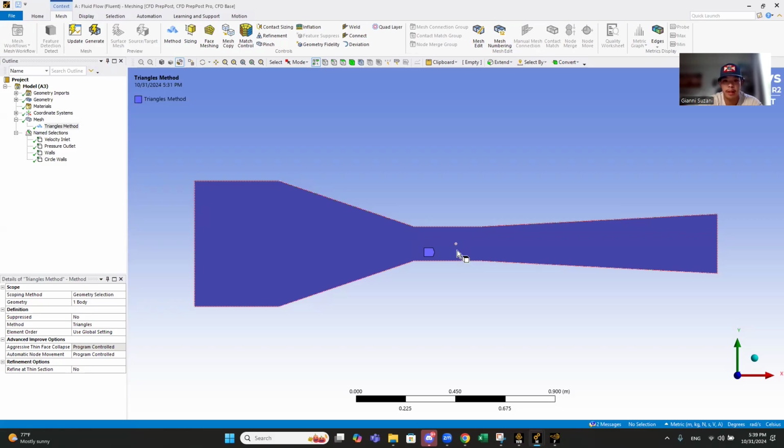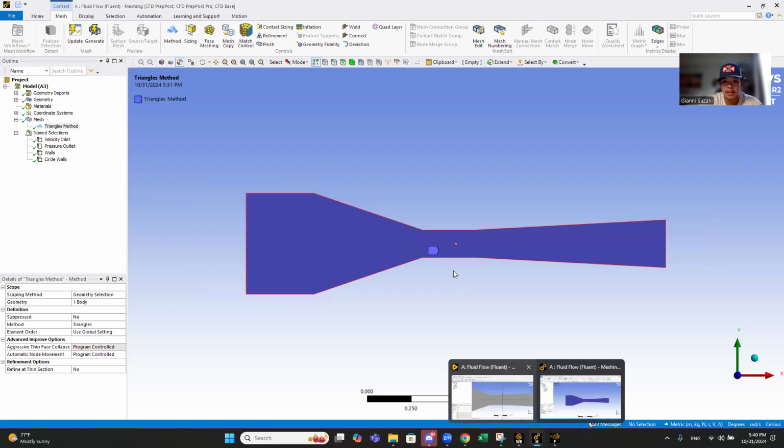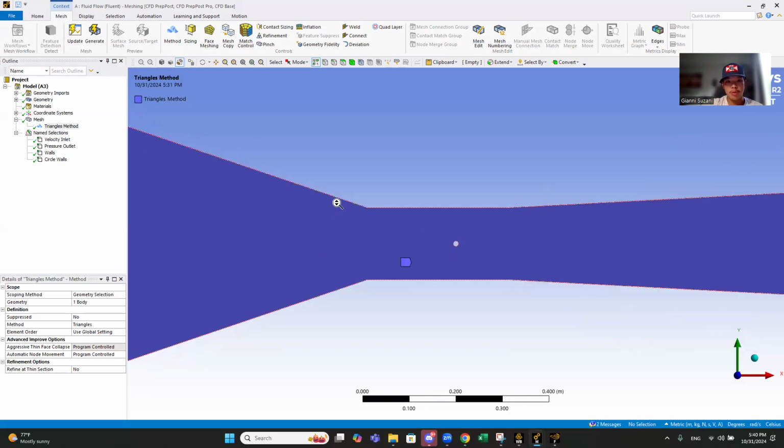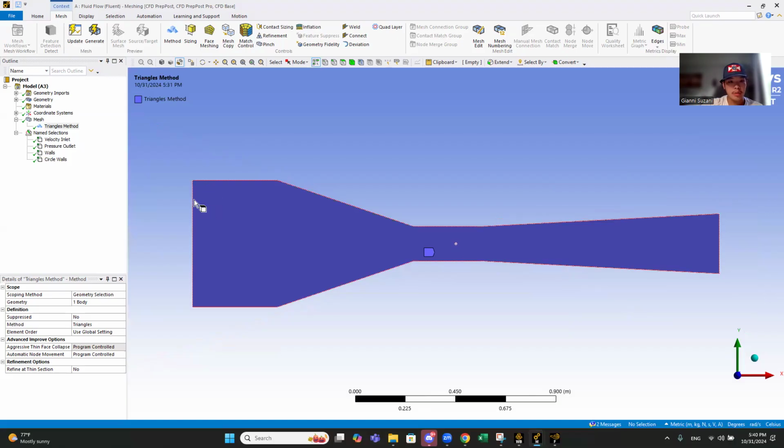Basically, you just draw a circle at the midpoint of the test section and make sure your diameter is the right dimension, which is what I measured in the lab, 10 millimeters. You should convert it into inches, which I did over here, and then also name your walls and wind tunnel.